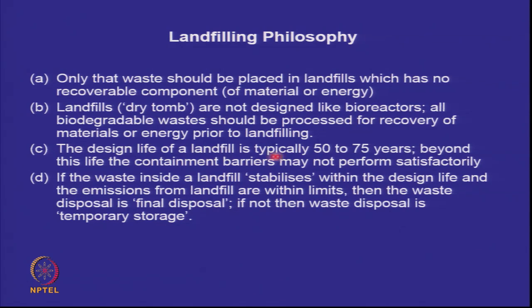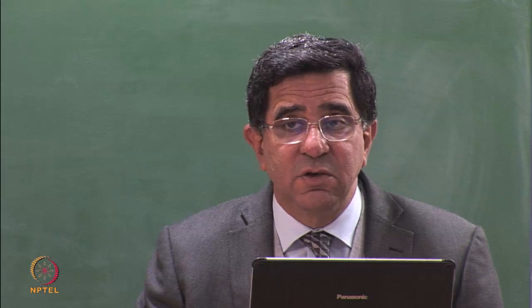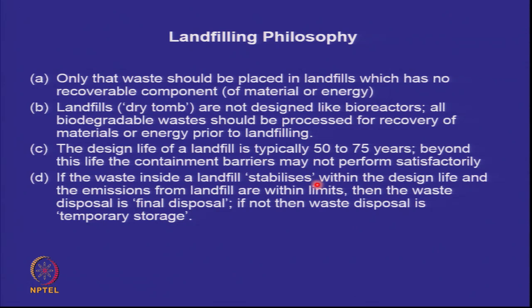And the design life will be typically 50 to 75 years, beyond which the containment barriers may have to be re-examined, and we may have to excavate the waste and reconstruct it if the waste is not stable. If the waste is stable, it can be homogenized with the ecosystem. So if the waste stabilizes, then the waste disposal is final. If the waste does not stabilize in 50 to 75 years, then the waste disposal is temporary storage.